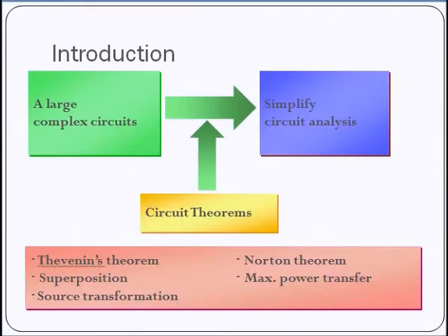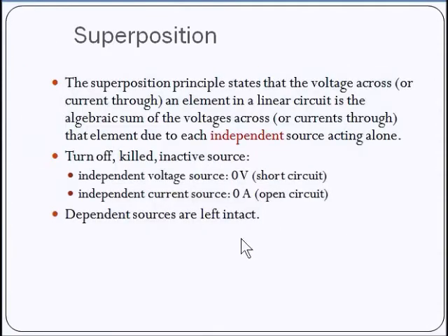Okay, so what is superposition? Sometimes in your test or examination, there may be a question asking you to explain what the superposition principle is. The superposition principle states that the voltage across or current through an element in a linear circuit is the algebraic sum of the voltage across or current through that element due to each independent source acting alone.